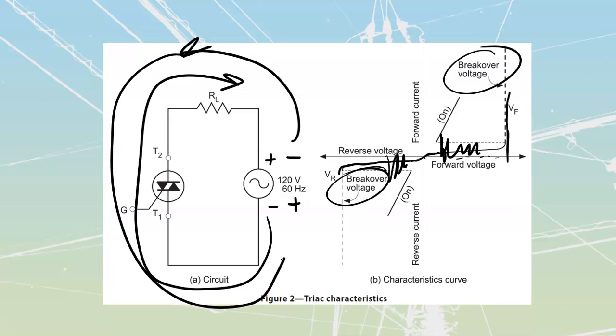Voltage drop across them is going to be relatively low as well. They don't take a lot of voltage. If I've got 120 volts, I'm going to see almost all of that 120 volts-ish over top of here. Really, we're going to drop maybe 2, sometimes 3 volts over top. Well, the book says a bit lower, but in reality, they're usually a little bit higher. So expect to see, at the load itself, maybe like 118 with 2 to 3-ish over top of that actual Triac.